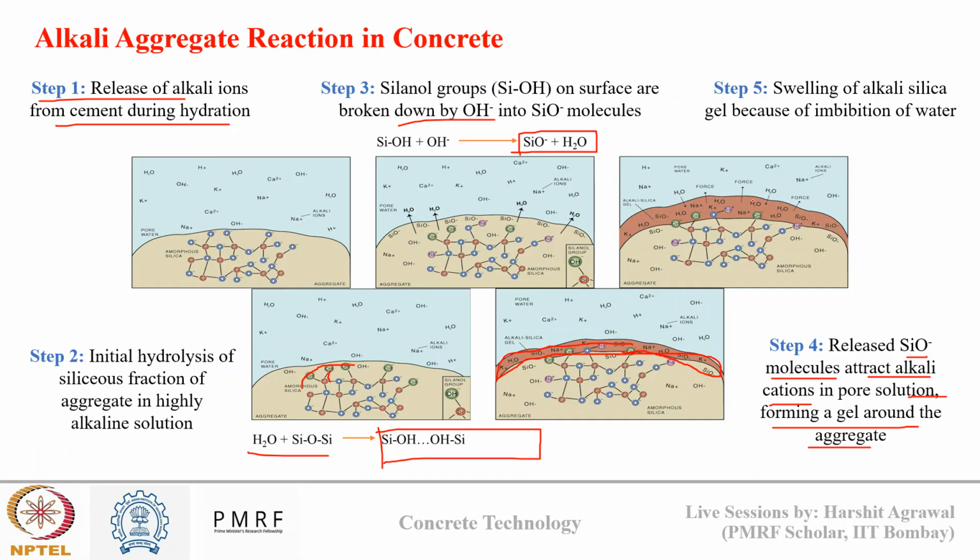So this gel has the capability to absorb water, and if it absorbs water, it will start to swell up. And since it is expansive in nature, and my concrete has a very restrained pore structure, this expansive nature will lead to cracking in concrete, which will cause the degradation in concrete. So this is how alkali silica reaction happens.